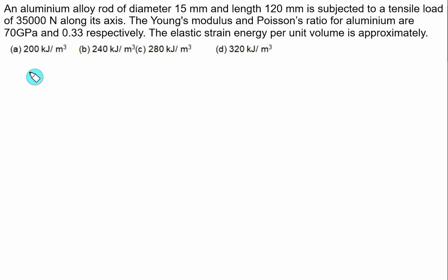So we have U equal to 1 by 2 into F square multiplied by L divided by area divided by Young's modulus E. We have to find the strain energy per unit volume, so let's divide by V on both sides. Volume is same as A into L, so L and L will get cancelled. So strain energy density is equal to 1 by 2 into F square, A into A is A square, divided by Young's modulus E.